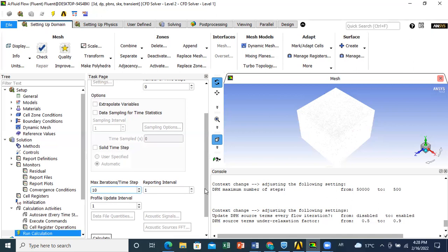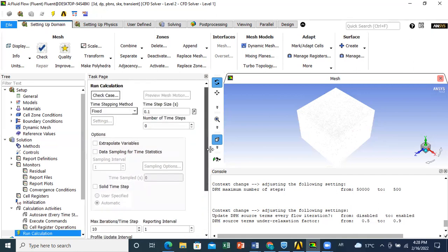And then after specifying these criteria, you should also select the total number of time steps you want to solve for. So let's say you want to do a simulation over, let's say, 2 minutes, okay? Then you determine how many time steps you should have in 2 minutes, and you enter it here. So let us put anything now. Let's say I want to do 1000 time steps. This means that I am solving for 100 seconds, okay, because each time step is 0.1. So I just multiply 0.1 by the number of time steps. I get that in total, I am simulating my system over 100 seconds.